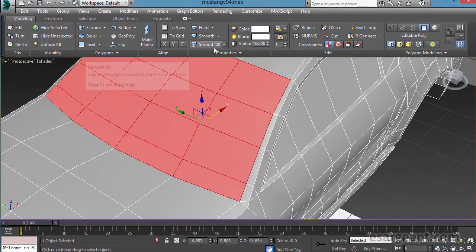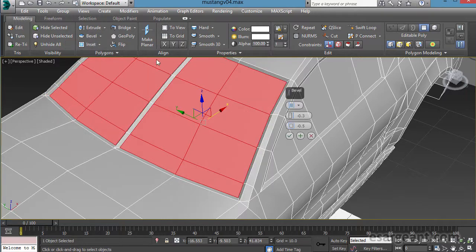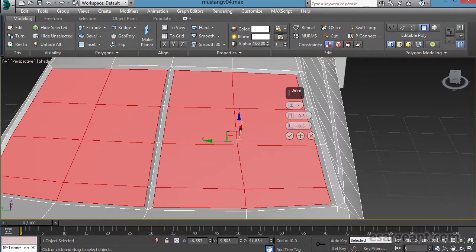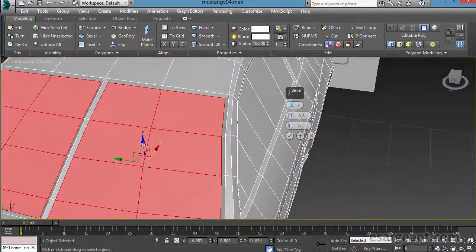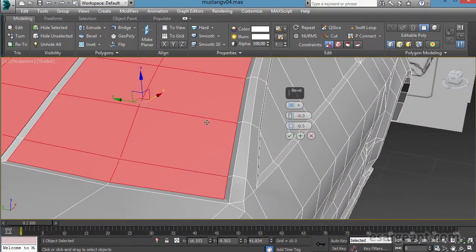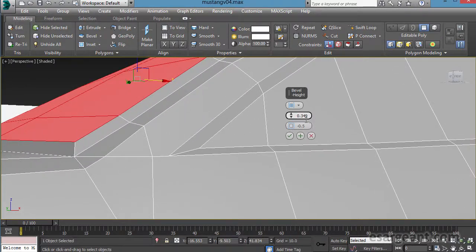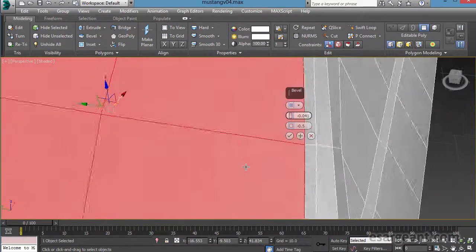Let's use our bevel again. Bevel settings. Okay, now this is interesting, because obviously we're only beveling half of this. We're going to get an interesting seam going down here. So this will require some cleanup later on, but that's not too big a deal. So what I might ultimately do, just looking at my reference imagery here, is that the glass is set in with that actual lip being a little further out. So let's try and replicate that if we can.